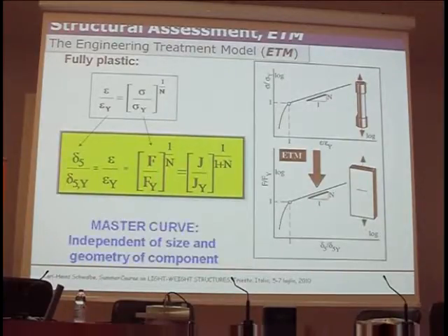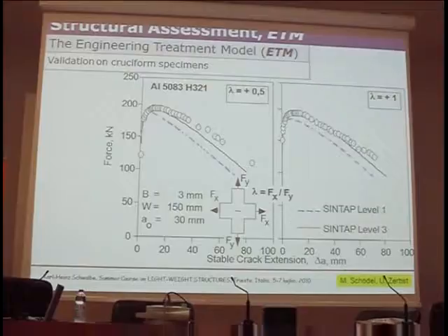Once again, everything is normalized, and the normalization gives us a description of the crack driving force independent of size and geometry of the component. So that's why we call it master curve. Now, a few examples for validation.